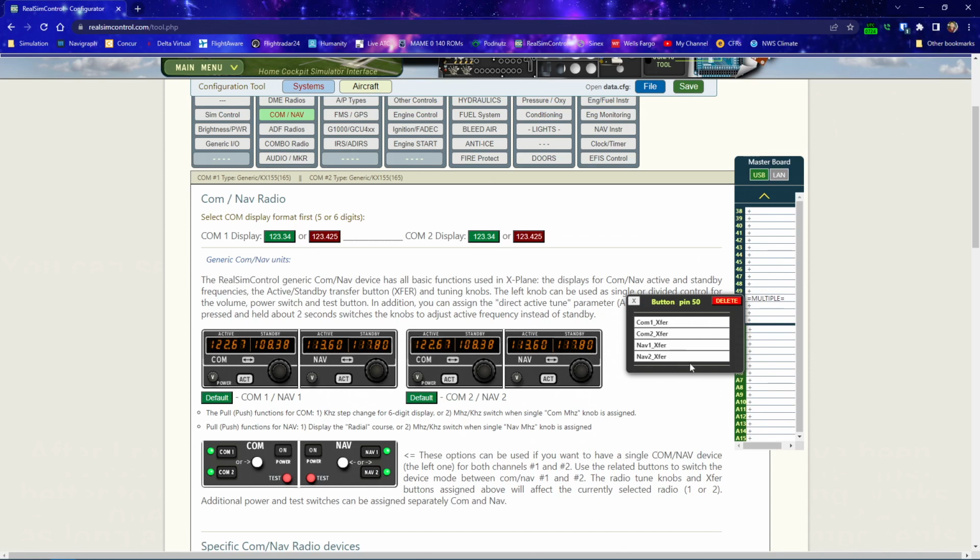Now you already have a selector, so what we need to do is tell this that we want to use it with selector number 1, and for each one of these you need to make sure that the mode is the position. So let's say the first position of the switch will always be 0, the second one will be 1, the third one will be 2, and the fourth one will be 3. So it's always 1 behind, because in binary, in computers, everything starts with 0. It doesn't start with 1. Okay, so now that's for number 1. So now we're going to do number 2.